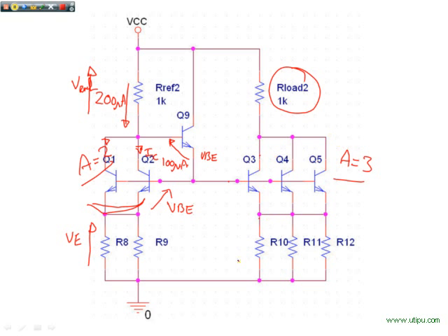Here we have our output stage load, just the same, and in this case we have some sort of degeneration and again VBE. So inside here you have one big Kirchhoff's voltage loop. You could have different VEs on each side of the input and the output, or if you want to be a little smarter, all of these VBEs across all transistors will be identical if you keep the current densities the same.